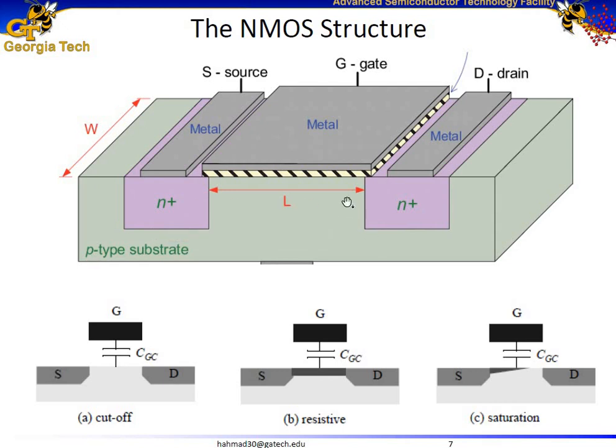So basically we have a capacitance between the gate and the bulk under cutoff conditions, because under cutoff there is no channel. In linear mode of operation, we know that there would be a uniform channel running between the source and the drain. And here is another pictorial depiction of that. So in linear mode of operation, this capacitance is distributed between the gate and the drain, called the gate to drain channel capacitance, and between the gate and the source, called the gate to source channel capacitance.